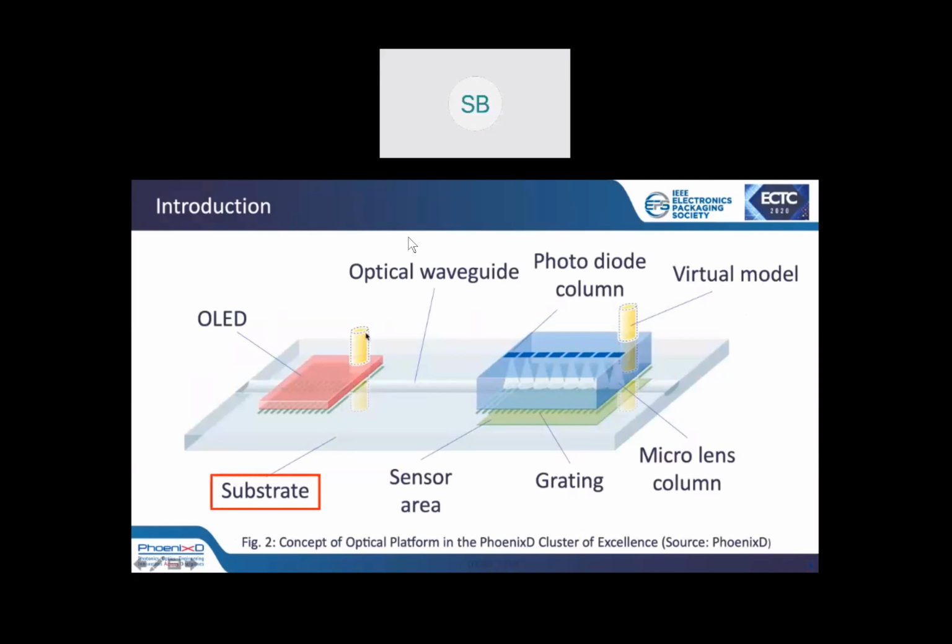Why did we choose gold as a reflective cladding material? We use a laser diode in our project of about 950 nanometer wavelength. If we look at the graph of the reflectance of surfaces of different materials, we can see that for gold at a wavelength of 950 nanometers, we have a reflectance of about 99.4%.